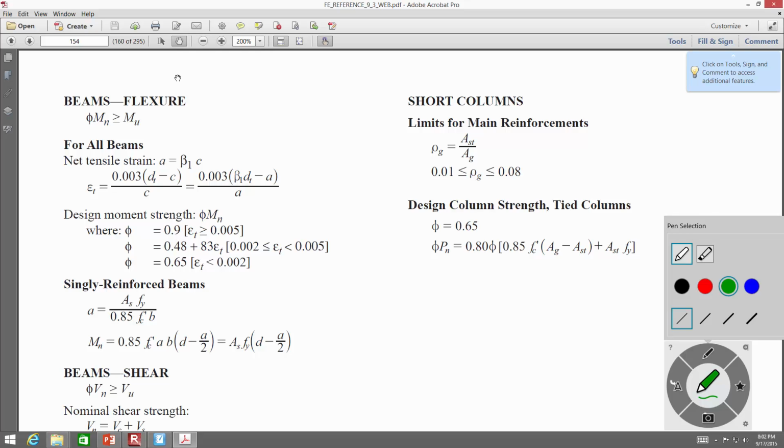That's one way of shoring it up. Another way is it's highly likely that phi is 0.9. I'm not saying ignore it, but you could probably just assume phi is 0.9 instead of having to do the strain check. You assume it at your peril, but it is not the craziest assumption in the world. If you're running out of time and have one of these problems, then just go ahead. So really what you could do is calculate your moment as PL over 4, times 0.9, and solve.